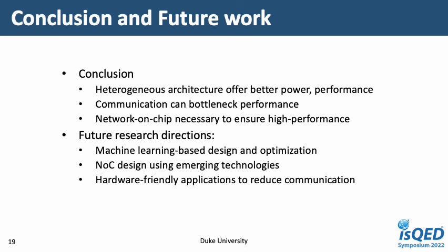And in the case of the ReRAM GPU based communication, we saw that the traffic is multicast based and it has to have high throughput between the ReRAM and GPU. Now, if our design is not aware of this, we can have suboptimal performance. So we definitely need to address this, and designing a good network on chip is needed to ensure high performance.